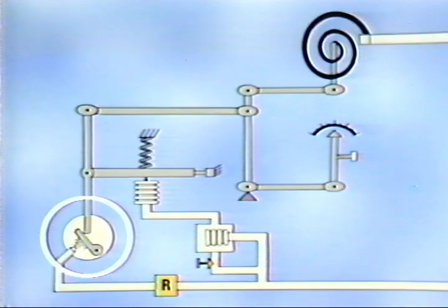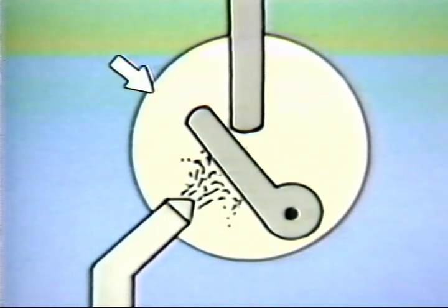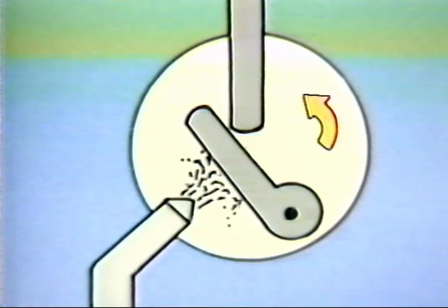Any movement of the link and lever assembly repositions a flapper relative to a nozzle. The flapper-nozzle arrangement is the error detector mechanism. Both the flapper and nozzle are mounted on a rotating disc, which is the proportional band adjustment.